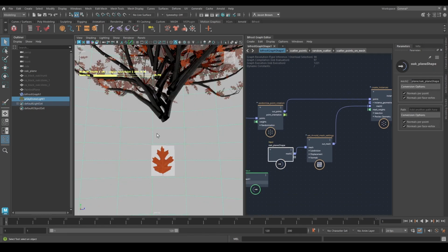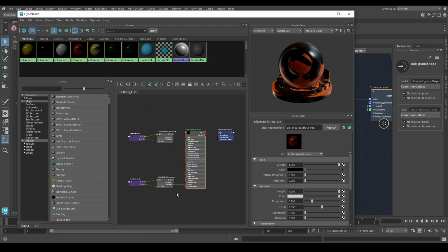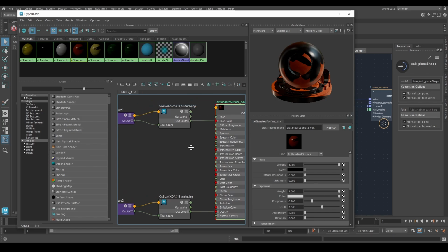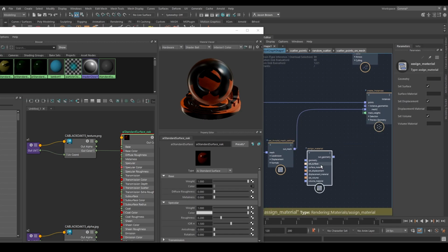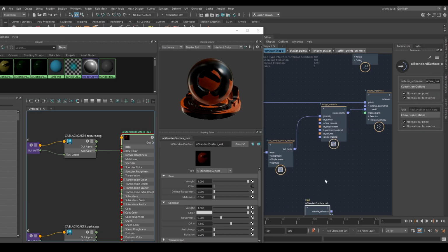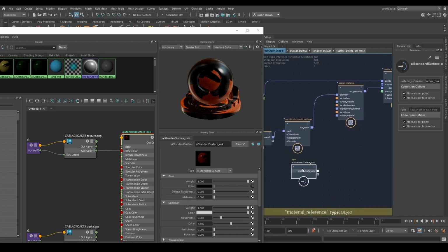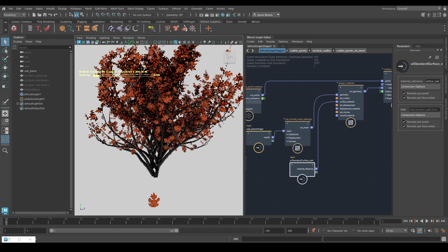There's the shader right now. We're going to have a very quick Maya lesson. I'm going to go to my hypershade. It is Aspen, and I need oak. So this is the shader we're using. You can see it's got an alpha channel. It's got a texture, so I can assign material. It goes into the geometry, comes out there, and I can quite simply middle click and drag this across to here. So this is this shader inside Bifrost, and then set that to my surface material. Because our material is correct, we now have leaves on our tree.